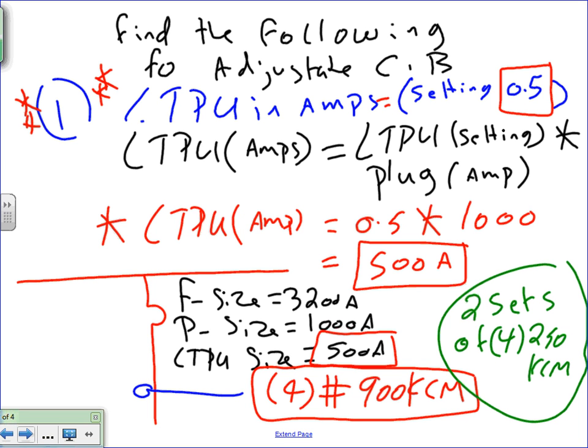Based on this electronic circuit, your circuit breaker can be one size or another. What gives you the range? 10% increments, 100%, 500, 1,000, 0.5 or 50%, 500. So we could really change out our plug to go higher for our frame size, or lower. Your limit for the plug size is the size of the frame. You can't go higher than the frame because physically you can't fit.